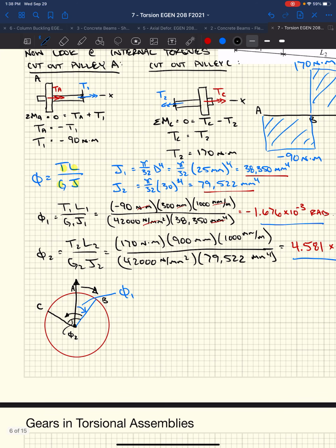So finally, we're going to get to point C. So the deflection at C relative to A is this deflection. A to C: from A to B, we went one direction. B to C, we overcame what we did from A to B, went back the other way to C, and now we really want to know what's that difference between A and C.